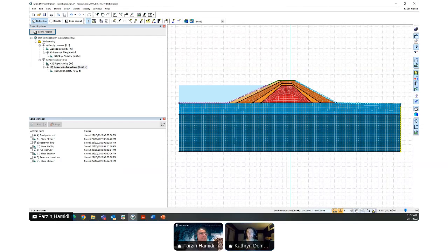And that means that the SIPW solver doesn't have to try to find a solution. The convergence issues are caused because the hydraulic conductivity within the drain is so much different than typically the material beside it. Sometimes we see these very low conductivity materials alongside the drain. And so it's that presence of those two different hydraulic conductivities that can really cause issues. But by placing a potential seepage face there, instead of trying to calculate the pore water pressures and the corresponding hydraulic conductivities within those two different materials, you don't have to do that. And so that helps to alleviate some of those convergence issues.